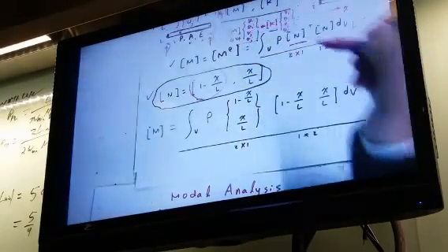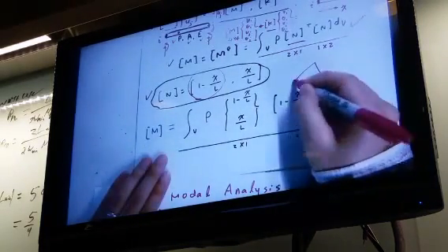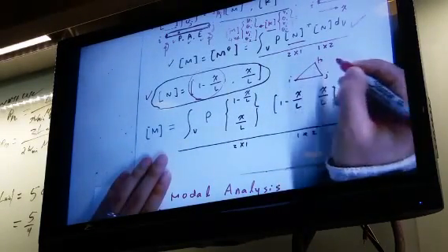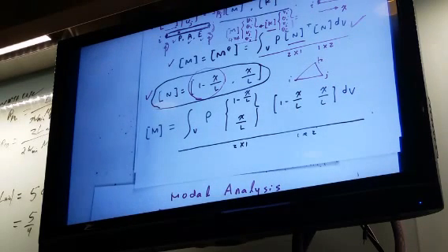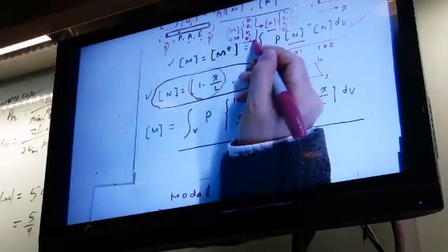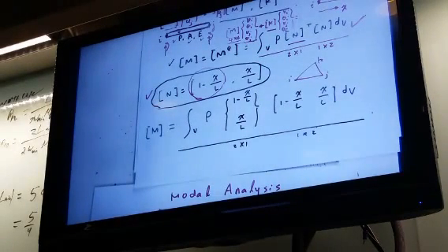If you have 3 joints for a triangle, that is one piece of plate. For example, this is one plate, IJK. Okay, this is one piece of the plate, and this is one element. In total, you have 6 degree of freedom. Each joint has 2 degree of freedom. So this one becomes 6 by 1, and then you are going to need to form a 6 by 6 M matrix. So this is a procedure.